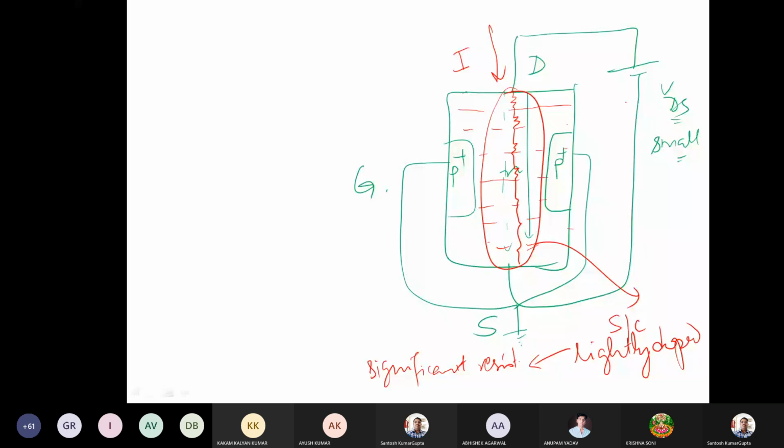Due to this VDS applied, we have already said that the charge carriers start to flow and they will form the current. The same amount of current is going to flow through all the sections coming in series. So these will make some voltage drop here. Due to these voltage drops, these different section points can be said to have different voltages, and these voltages can be found by the voltage divider rule.